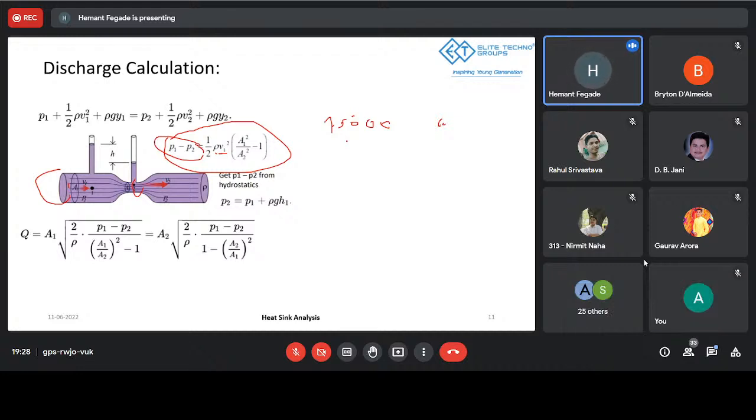By defining your mesh properly, applying a different set of boundary conditions, and different solvers or models, like k-epsilon and k-omega models. You can use different models to test your theories and try to reduce this difference. Once the difference is very minimal, let's say you are getting 75,000 theoretically and 71,000 with the numerical value, then that is acceptable.